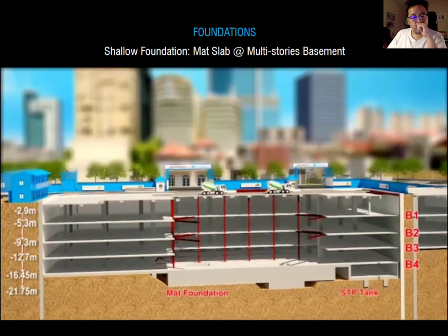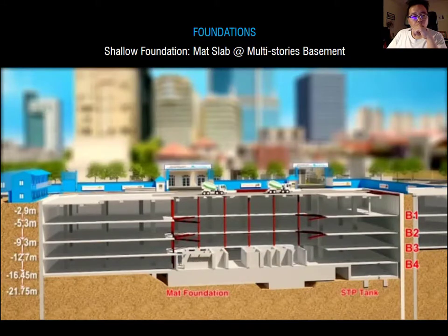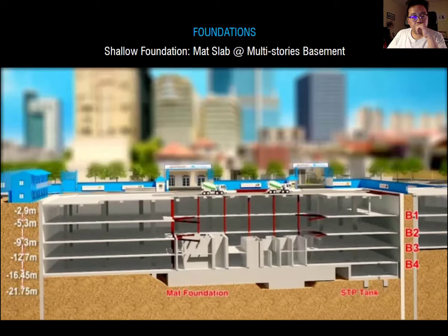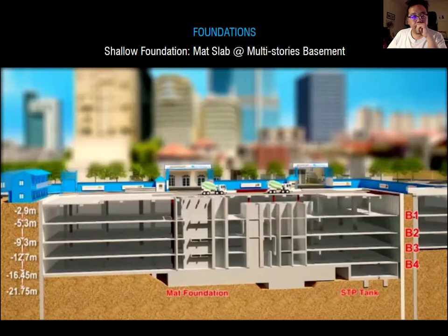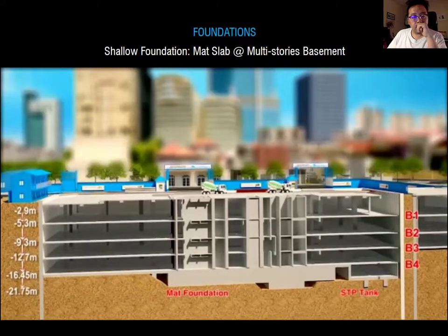Remove temporary struts at basement 4 level and reinforced concrete for columns, then the core will be constructed over the mat basement slab. Basement 3 slab at opening area. Sequence as above. Huabin Corporation will remove temporary struts and cast concrete for shear walls and slabs from basement 3 up to level 1 in opening area and construct ramp and stair at the same time. Finally, remove king posts outside the column.